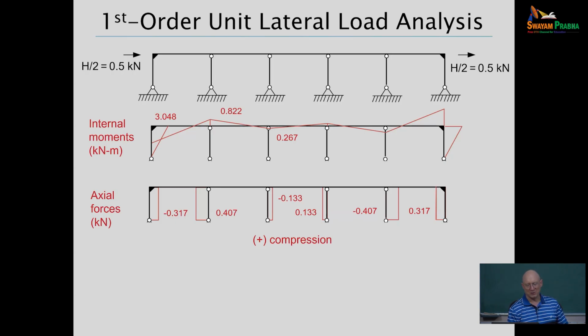What I want to do is a unit lateral load analysis on the structure and document what moments and axial forces I'm going to get. And then for whatever values of lateral load I need to work with later, I can multiply by the results for the unit lateral load and add the effects up.